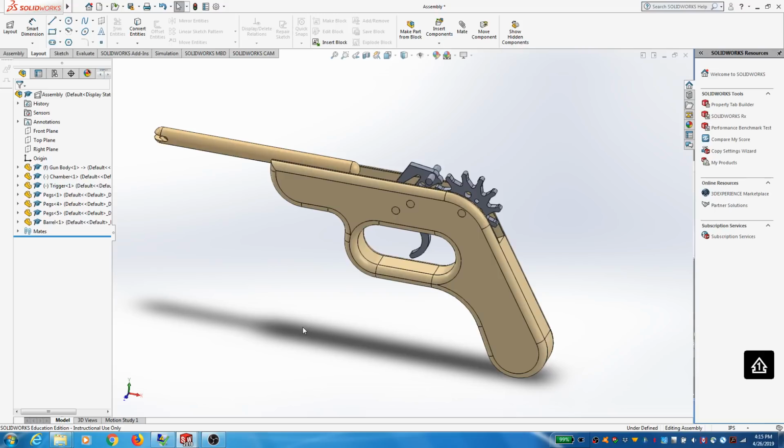This is a rubber band shooter. So it's a system here that consists of a body, right, a barrel. This one here we are calling the pawl or the trigger, and this guy here we're calling the chamber or the ratchet. The mechanism that is used here to advance, so what happens is you load the rubber bands over the back of this barrel here, and you stretch them over the front, and you're going to squeeze the trigger. This is going to pivot forward, and it's going to launch the rubber band off of the front.